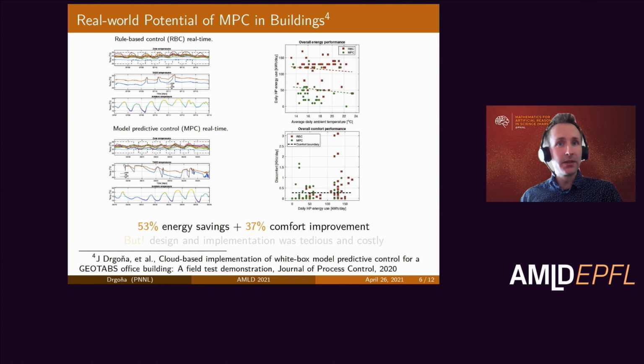While the story is very different under model predictive control, these control actions are highly dynamic because they adapt to different scenarios. They take into consideration the time of day, desired comfort, the future forecast of the ambient temperature, the weather forecast, and basically an estimate of the internal energy in the building. So that's why we gain so much, because a complex decision is far more powerful than simple rules.